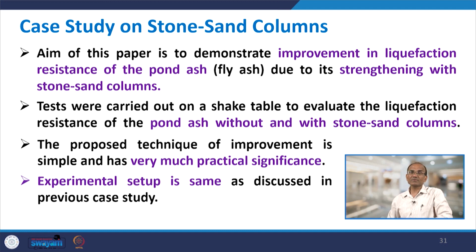Tests were carried out on a shake table. Again, the test was conducted on a shake table to evaluate the liquefaction resistance of the pond ash without and with stone sand columns. The proposed technique of improvement is simple and has very much practical significance. The experimental setup used in this technique is the same as discussed in the previous case study, that is, the same shake table has been used.